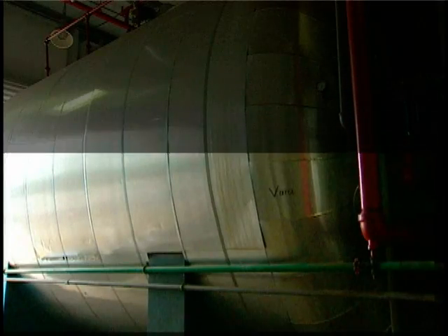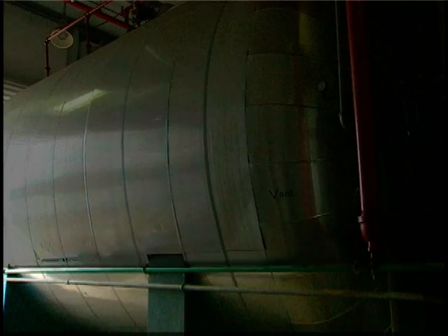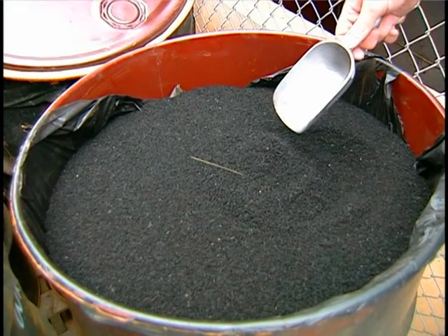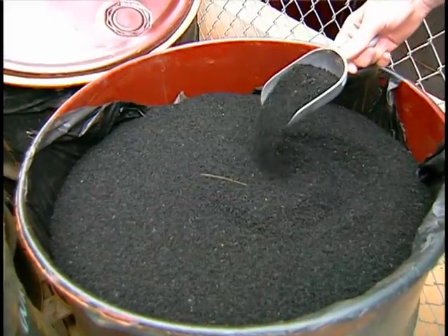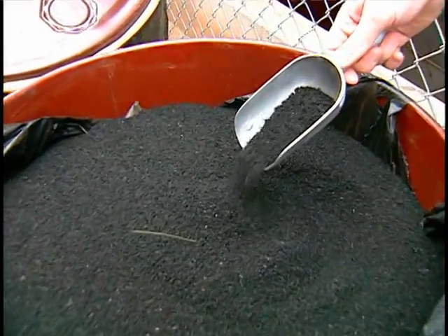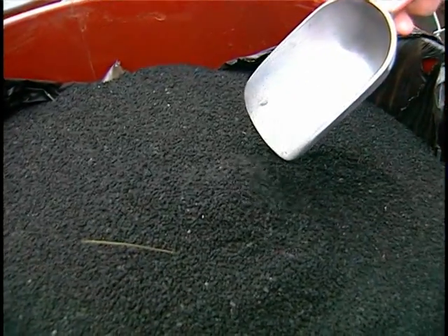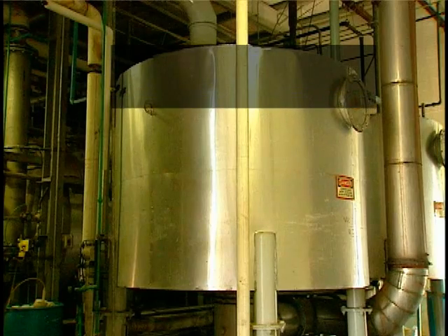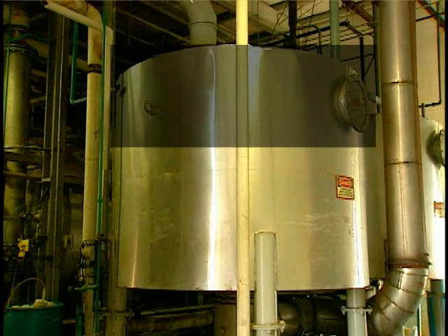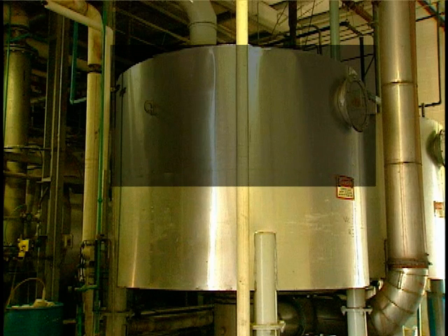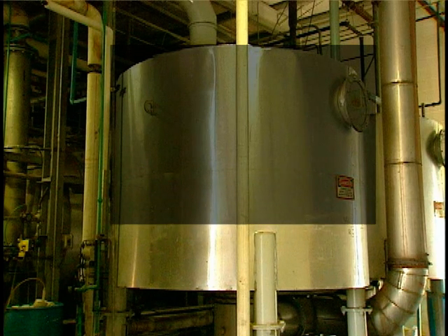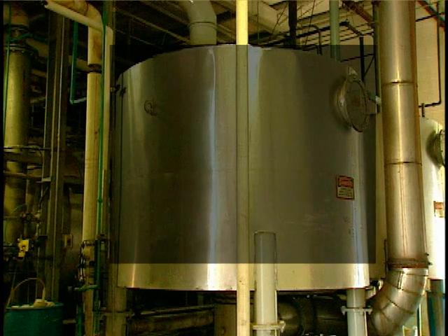Retention also increases as the organic concentration increases. However, more total carbon is usually needed at higher concentrations because of the greater quantity of organic contaminant that must be collected. Retention is affected by the molecular weight of the contaminant molecules. As the molecular weight of the molecules increases, retention increases.